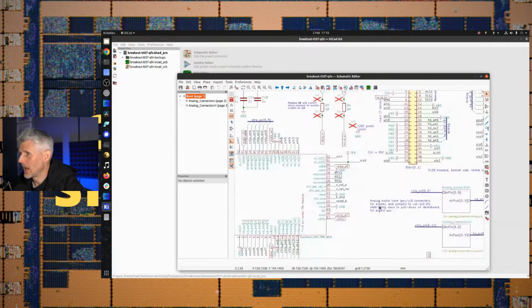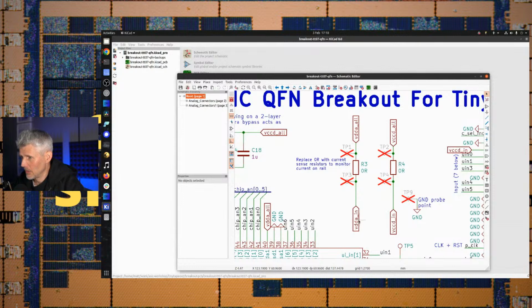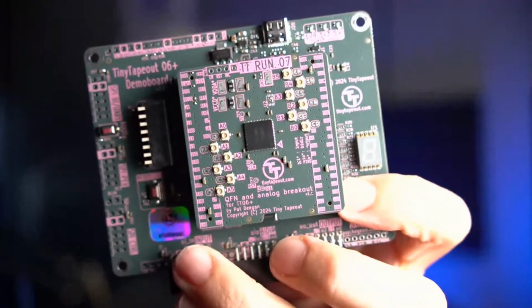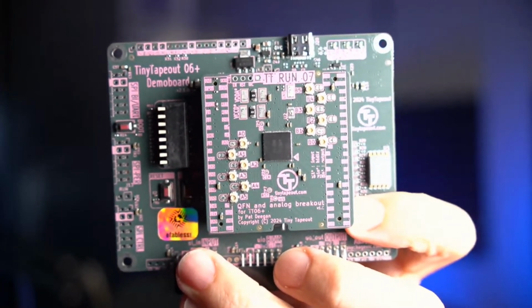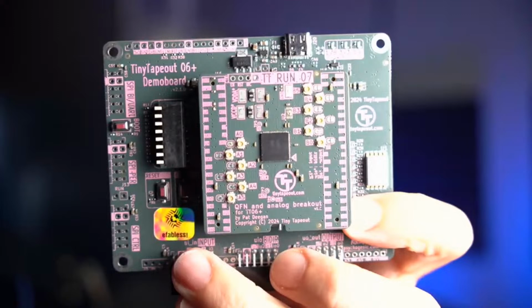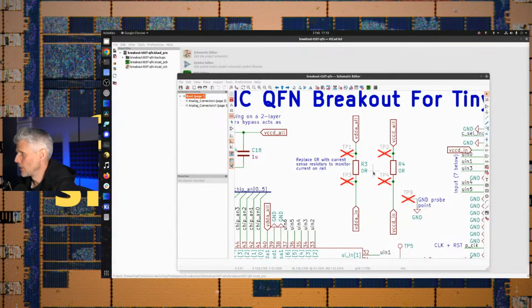and that's also got a very convenient 0 ohm resistor placed here. You can actually see it. Maybe if I just remove this temporarily. On the top of the demo board, those 2 big resistors on the top there, they've got a 0 ohm resistor placed there. So you can remove that. That's it here, R3 and R4. And then you can supply your own VDDA.